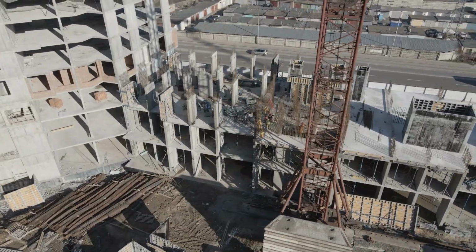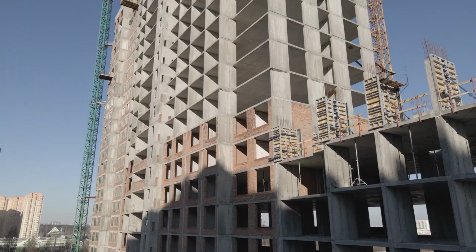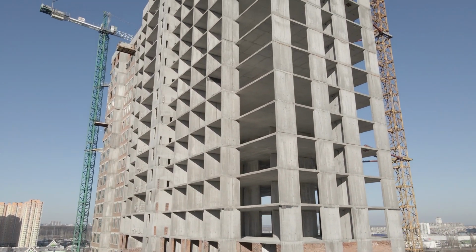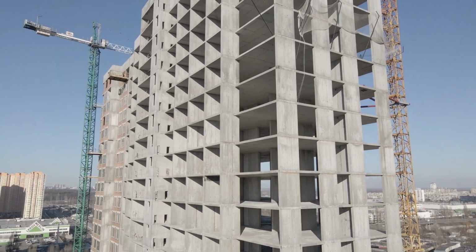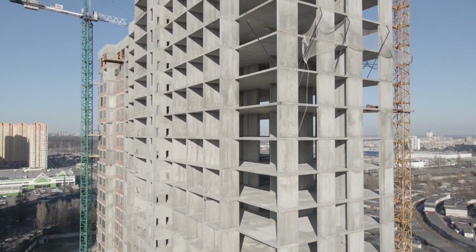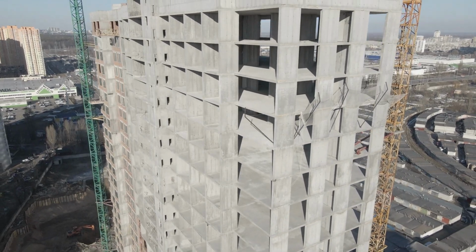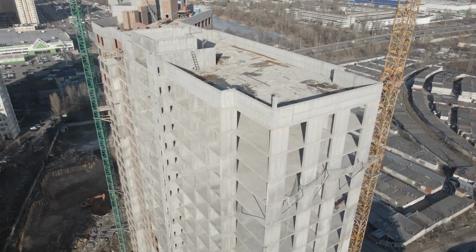Requirements of a good formwork. It is very important that the formwork is well supported and strong enough to bear all loads applied to it. Formwork must be aligned and braced well from all sides to keep its original shape. It should be watertight to prevent the leakage of cement grout. It should be constructed in a proper way so that at the removal stage, concrete can be safe.